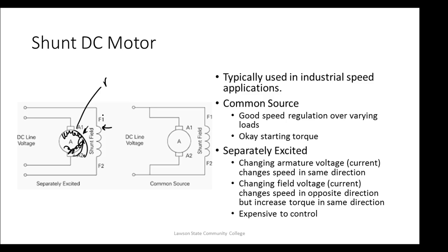And that's what you want. When the motor is sitting still, you have no counter EMF, so you get the full strength of the field and create a bunch of starting torque, right? But as the armature comes up to speed, that induced voltage subtracts from the voltage being applied to the armature and causes the motor to produce less torque. It runs at a speed that generates enough torque to run the load. So most people say the R of the armature goes up, and that's true, but it's doing it electrically, through what we call counter EMF.